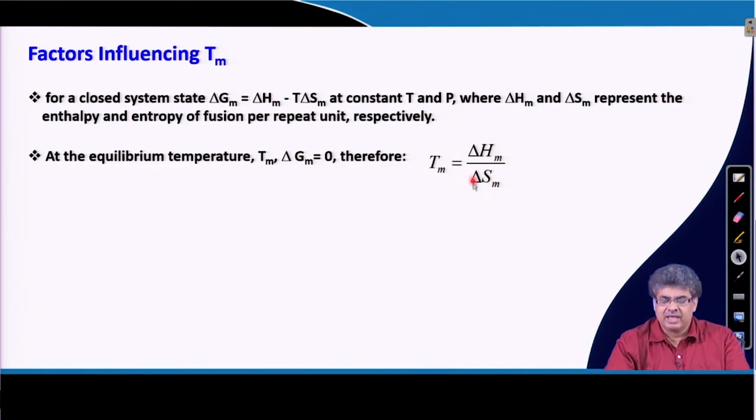Now, as the polymer chains go from a molten state, when we cool it and it forms a crystalline domain, the polymer chains, having a random orientation and being much more flexible, become stiff and oriented in arrangement.